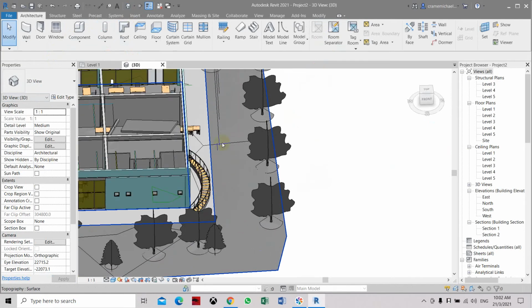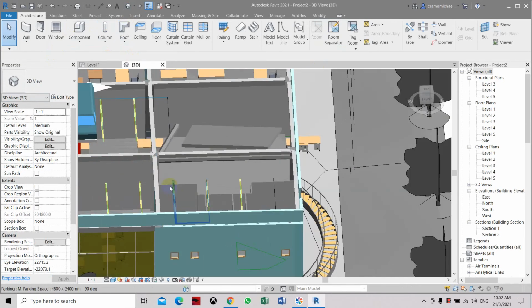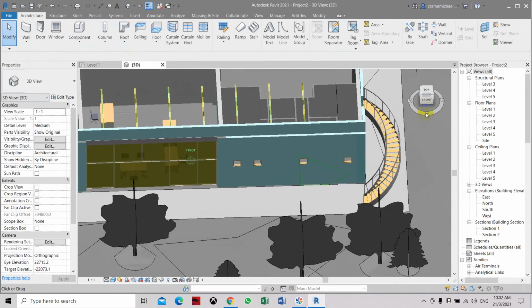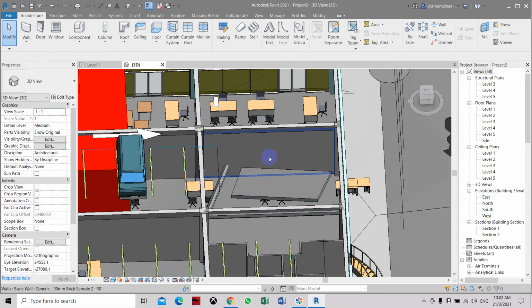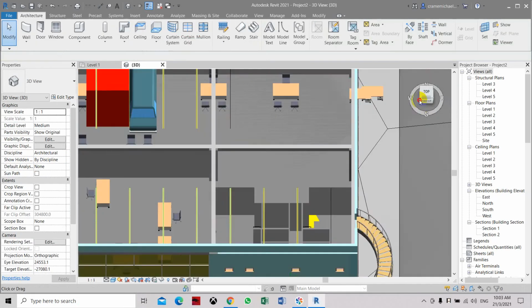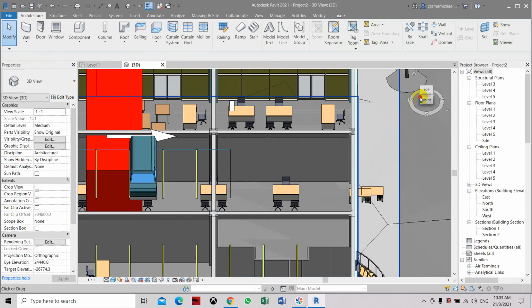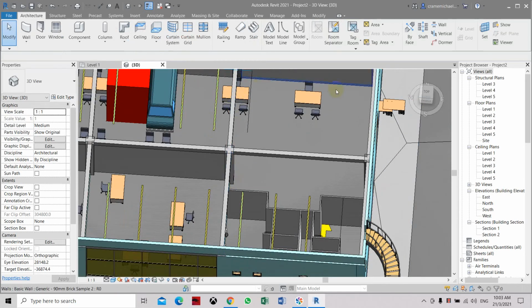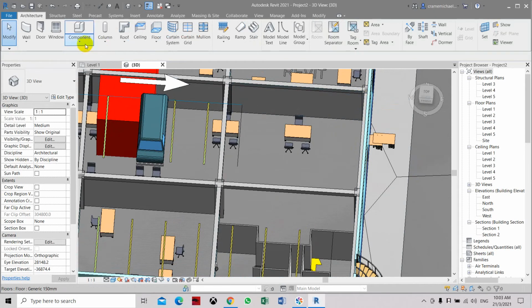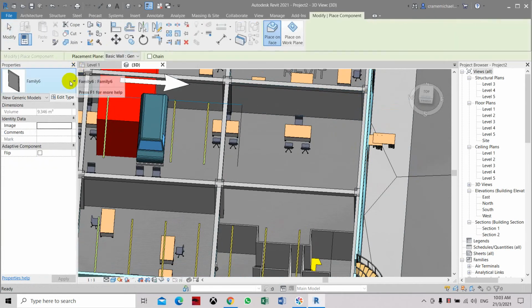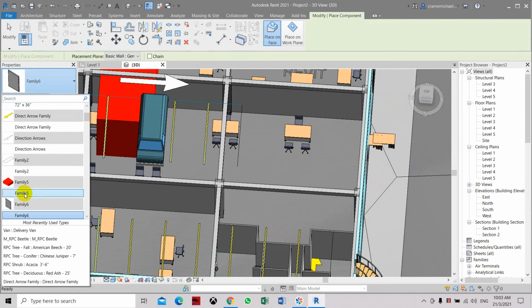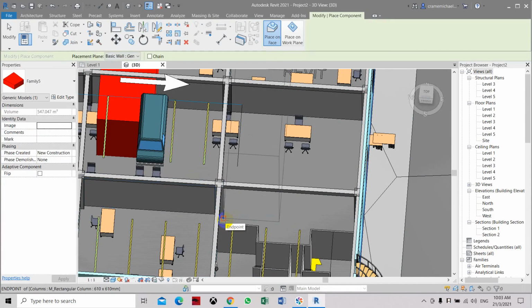So let's create that placement of that object. Let's say we have 3D, one on the floor level and one on the high level. So let's delete these items first. Let's say I want to place that object from this column to that column, edge, and then top. So let's place that. The family file, we're using the family file. So let's place this column 1, 2, and then let's set the height on this top 3 and 4.